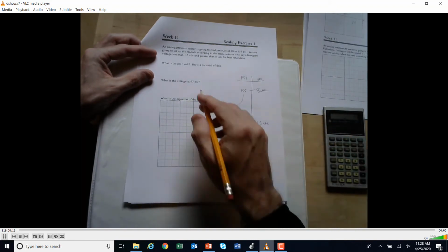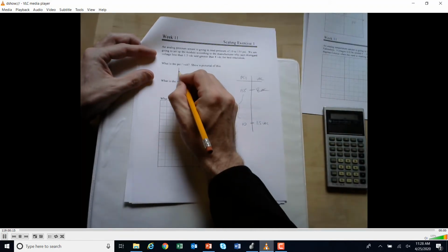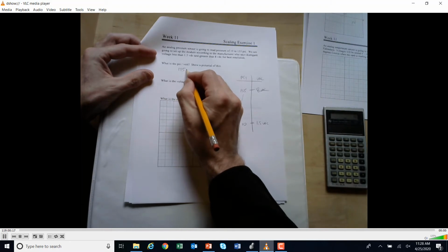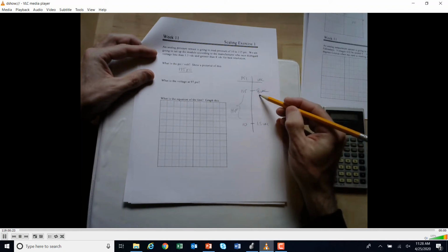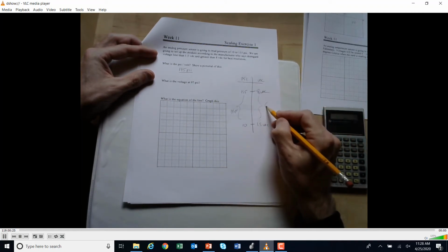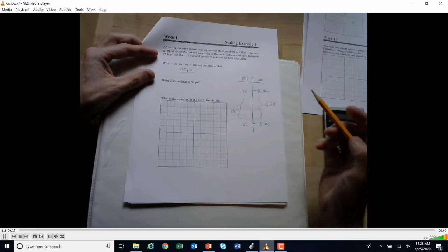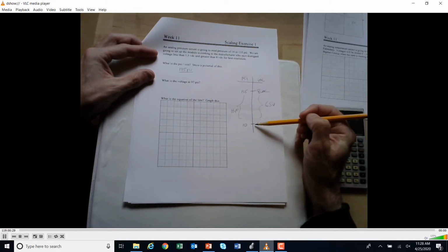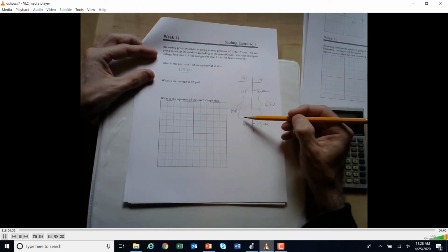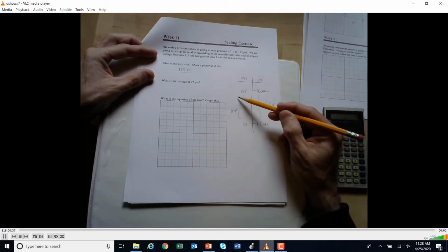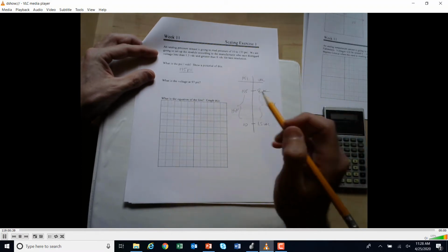Okay, so psi per volt: we get 145 psi, and our voltage range here is 8 minus 1.5, so it's 6.5 volts. If we were all the way down here at 10 psi and we added 6.5 volts up to 8, we'd have to add up 145 psi. So there's a ratio here. And so what is it?